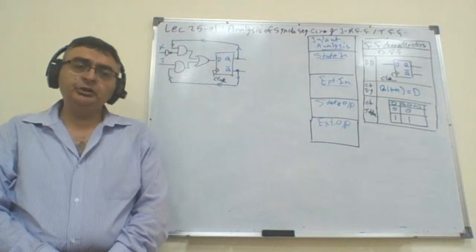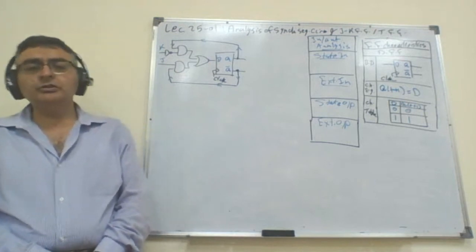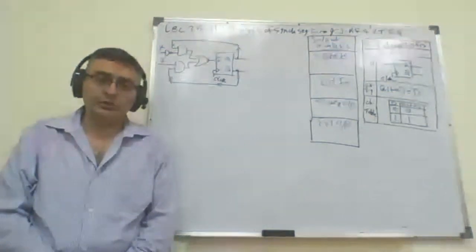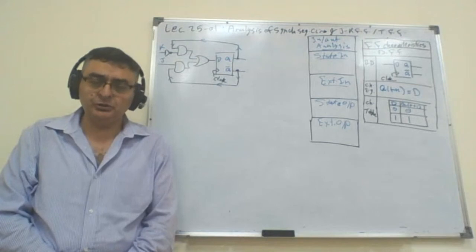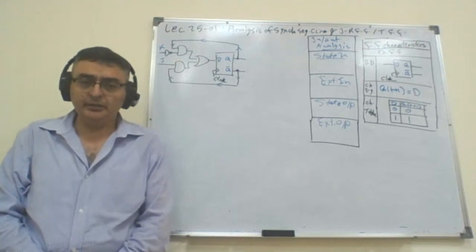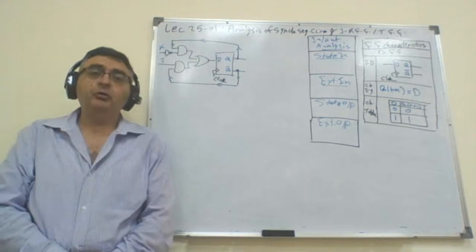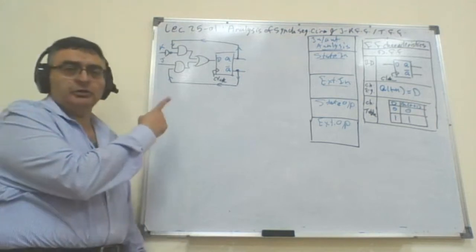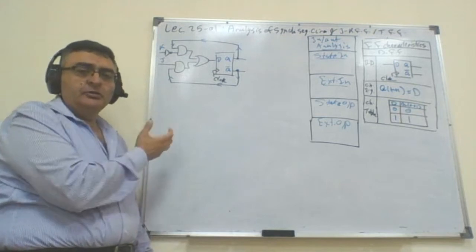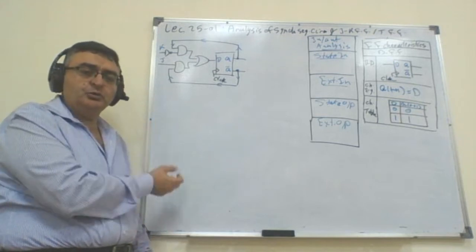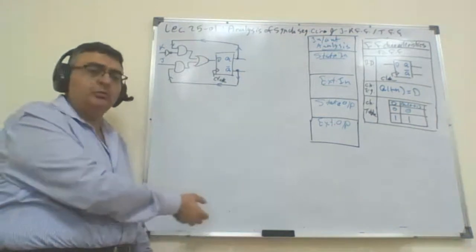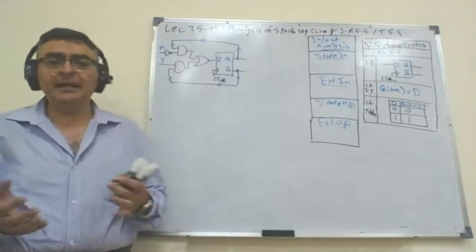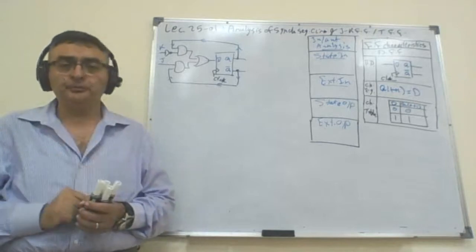2501. We continue with more advanced and more practical circuits in the synchronous sequential circuits. As we indicated in the last lecture, we have four components for synchronous sequential circuits. We have the circuit diagram. From the circuit diagram, we want to derive the state equations. From the state equations, we want to build the state table. From the state table, we want to get the state diagram, which completes the analysis. So we are in the analysis flow.